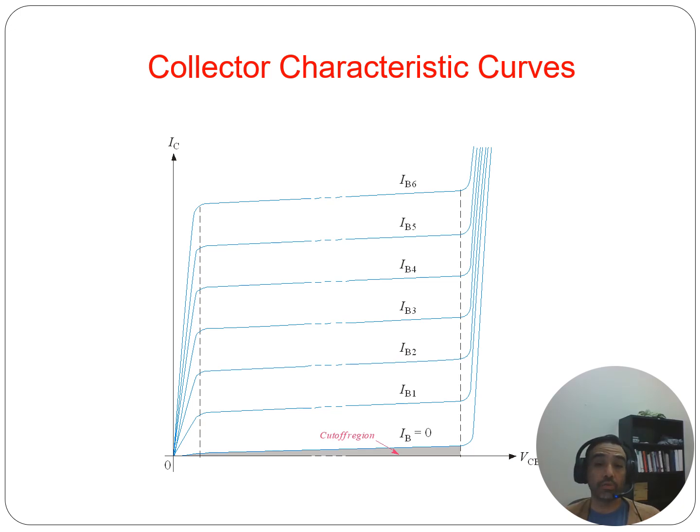And so how do you use the curves when you want to design? You can use the curves to decide how the transistor is going to work in your circuit. So if you want the transistor to act as an amplifier, obviously you need it to be in that active region. If you're troubleshooting a circuit with a transistor and your transistor isn't working as you expected, assuming the circuit was designed correctly, you can look at these curves and that'll help you figure out if it's in the right region or if the VCE is too high. So yeah, let's keep going.